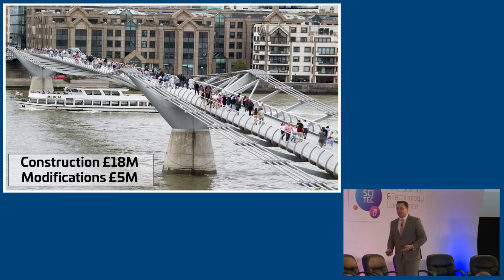Now, the reason for this was the way that the bridge had been designed. The natural frequency of the bridge is quite similar to the pace at which people walk. Also, the structural engineers, when they did the models, they didn't include the lateral forces that humans apply to the bridge as they walk. And that's what allows us to stand upright.